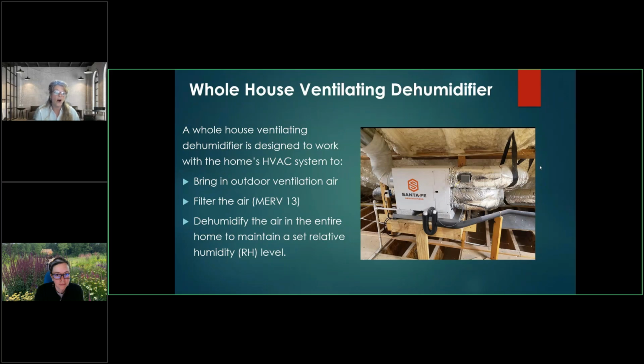But a whole house ventilating dehumidifier is designed to basically dehumidify the entire home, separate of AC runtime. You can bring in outdoor air if you want to do a slight positive pressure or supply ventilation through that dehumidifier. Then also we've got a MERV 13 filter in all of our systems. So the air conditioner can run based on thermostat. Of course, we want it right sized.